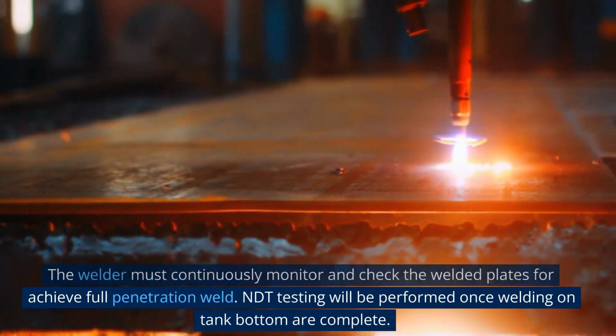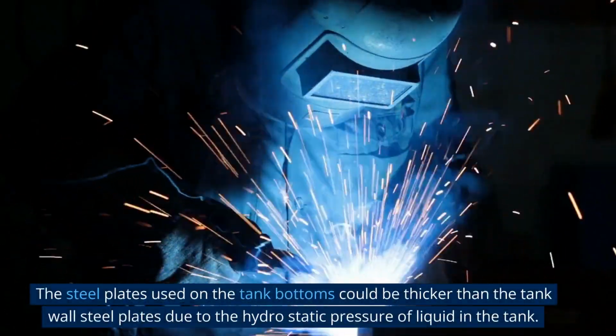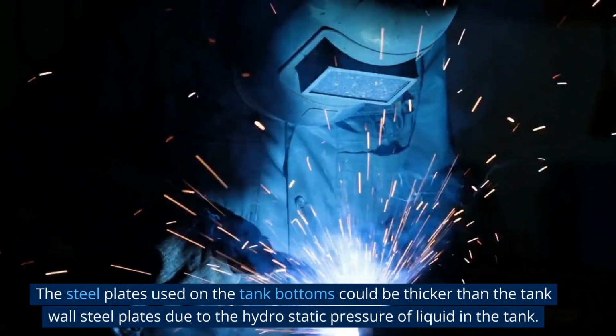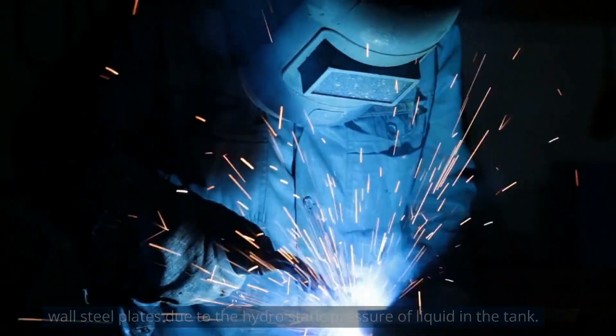NDT testing will be performed once welding on the tank bottom is complete. The steel plates used on the tank bottoms could be thicker than the tank wall steel plates due to the hydrostatic pressure of the liquid in the tank.